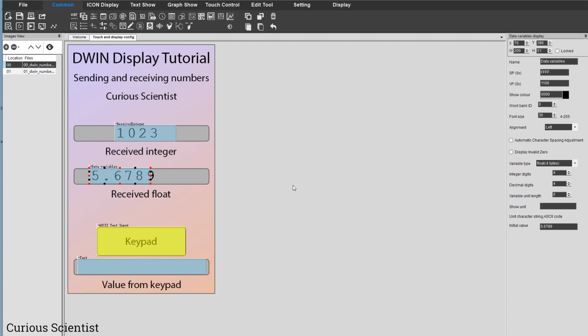Whenever I saw people build this general humidity and temperature sensor combo as a weather station, they always use integers for representing the temperature. However, the thermometer or the humidity sensor could show you at least one extra decimal digit. But it seems that people don't really understand, or I don't know, I'm not criticizing anyone here, but for some reason people are avoiding printing float. And I will show you why, because it's not that straightforward, but I did it. So you will know how to print a float.